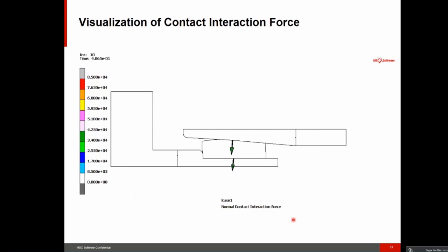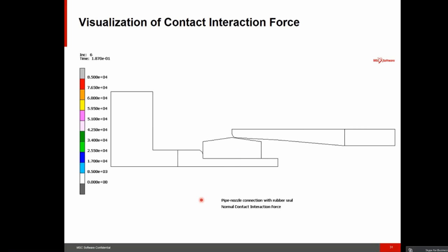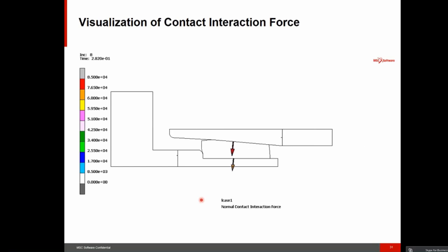And when we do, let's say, a visualization of the deformation of this body, we can say, also give us the interaction force during that process, and it will report that. It will make my little arrow plot at the nodes that I asked for. So this is quite useful if you just look at a single body. What you'll get is effectively a free body diagram of the contact forces on this particular part, which is very useful in the aerospace industry.